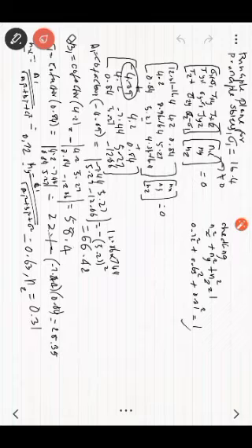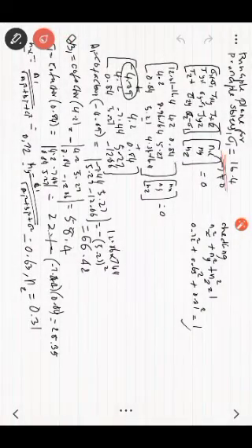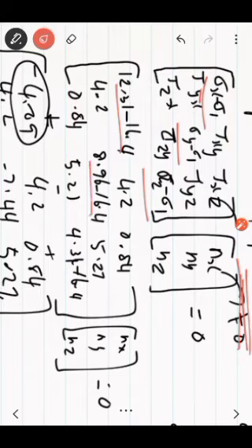So I extended the problem to find the plane for the maximum stress. To find the plane for the maximum stress, you have to consider this sigma 1 value itself and substitute it in the given stress. The given stress is this one. Substitute in that given stress the sigma, that is the 16.4 value, and subtract here and here. We subtract those values along the diagonal and multiply.